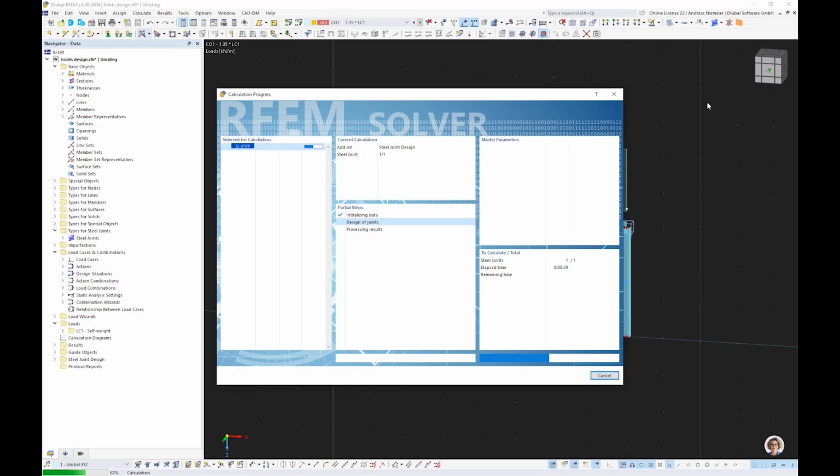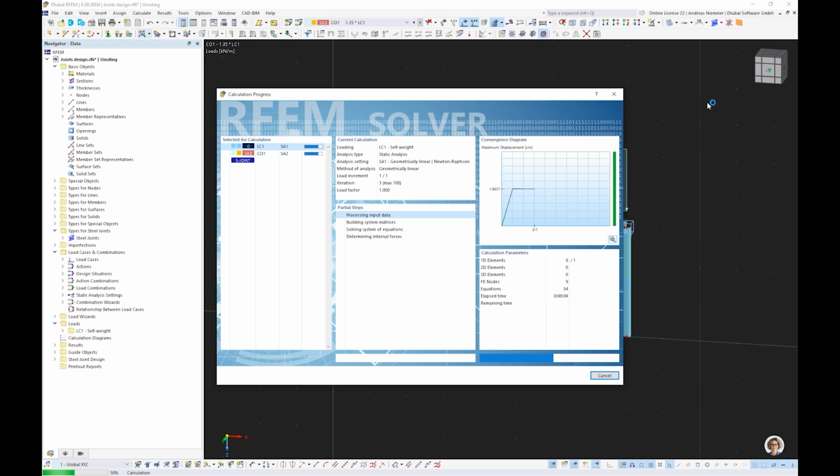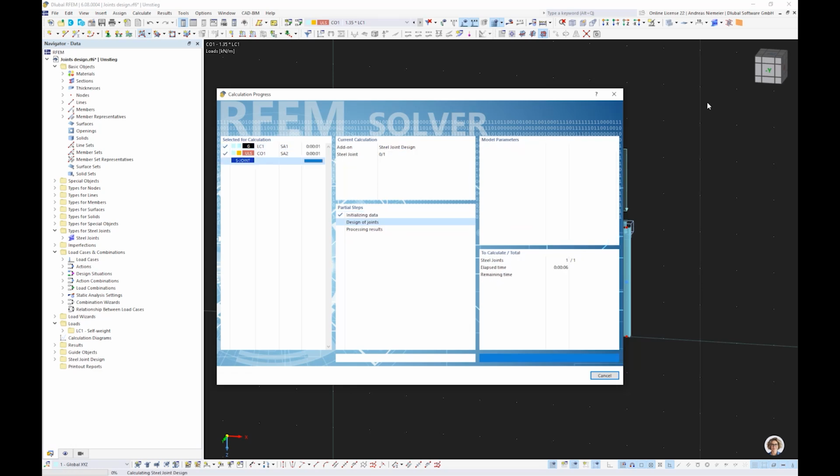Additionally, because this technology models behind a shell model with nonlinear material law, it checks the strengths in the end. This allows you to apply normal axial force, shear force in Y and Z direction, torsion moment, My and Mz bending moment. So you can apply all forces. It's independent. It's allowed. Yeah, and we use this with this concept. Further, you can analyze not only forces but also unit deflection, so we can calculate stiffnesses from it, and now new also assign it to the global model.